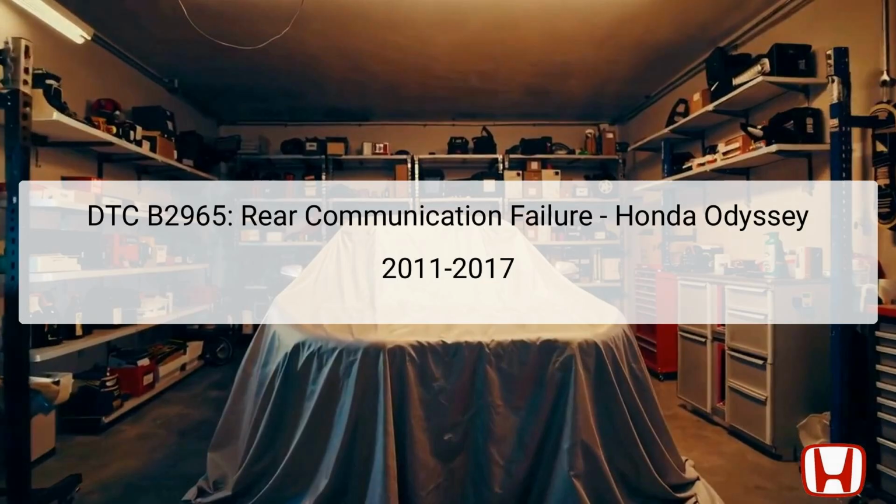The rear AC control unit is responsible for regulating the air conditioning settings for the rear passengers, while the HVAC control unit manages the full vehicle's heating, cooling, and ventilation functions. Faults can occur in the wiring or connectors associated with these units, leading to the DTC being triggered. The Honda Diagnostic System, HDS, is utilized for diagnosing this error, and resolving it often requires rigorous checks of electrical connections and the corresponding wiring.